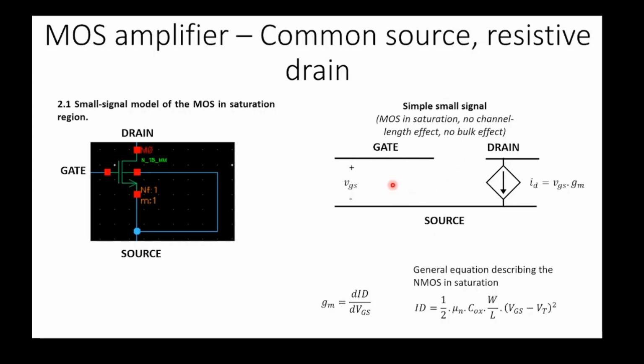This is an open and this is an open. Why did I put the voltage here? It just means that, in our analysis, we will put a voltage between the gate and the source. But actually, if I don't put any voltage here, the gate is isolated from the source and also isolated from the drain, just as illustrated in the symbol. There's the isolation here. And what about the drain and the source?